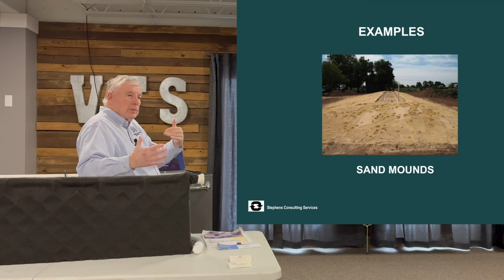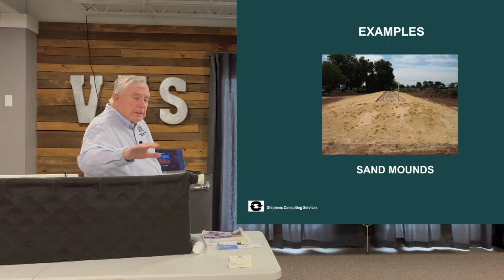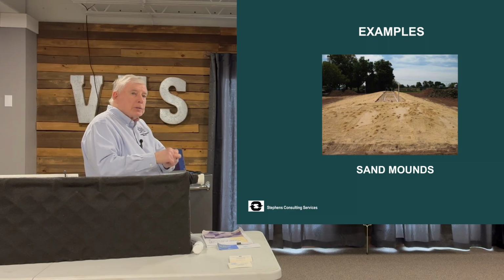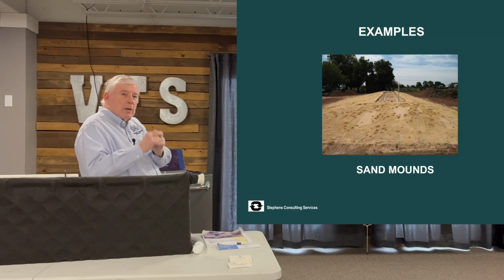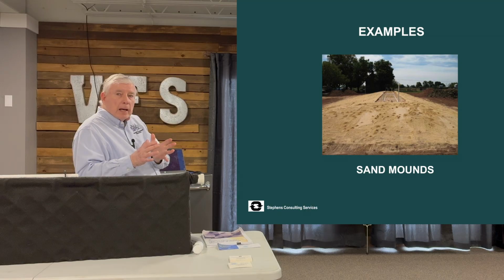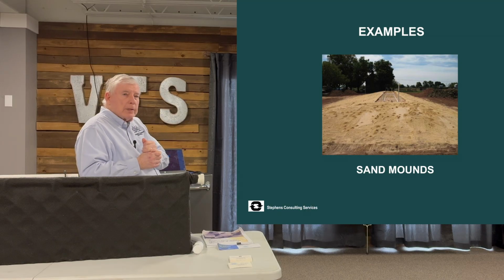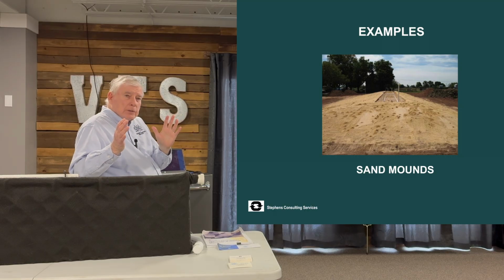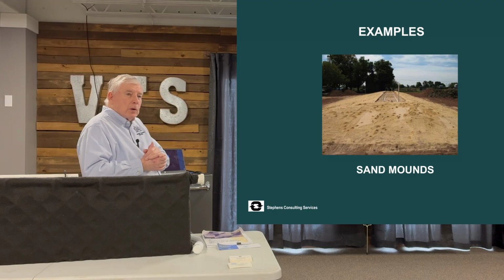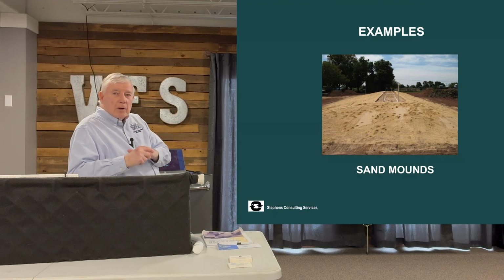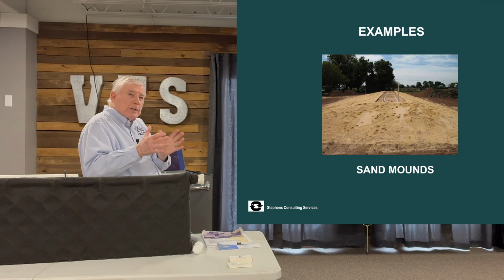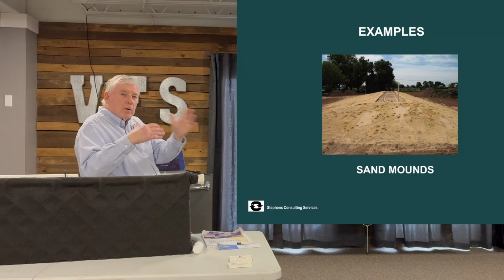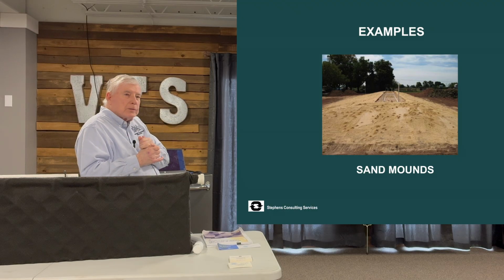The two are not directly related, but we designed this to use pressure distribution because I'm convinced we should be pressure distributing wastewater in every system if we want to get a good length of life, a good longevity out of our systems. And that's why I say we should design systems that last as long as a house, not just systems that last 20 years. With one replacement area, so that's 40 years. So if it goes as predicted, in 40 years you run out of systems, and you start going back and digging up and redoing the old systems.